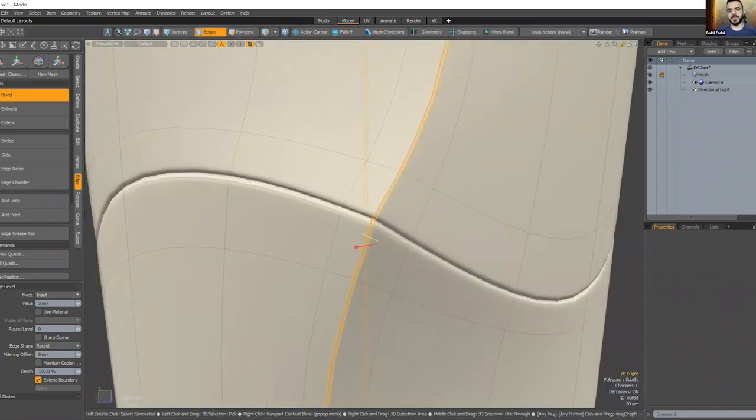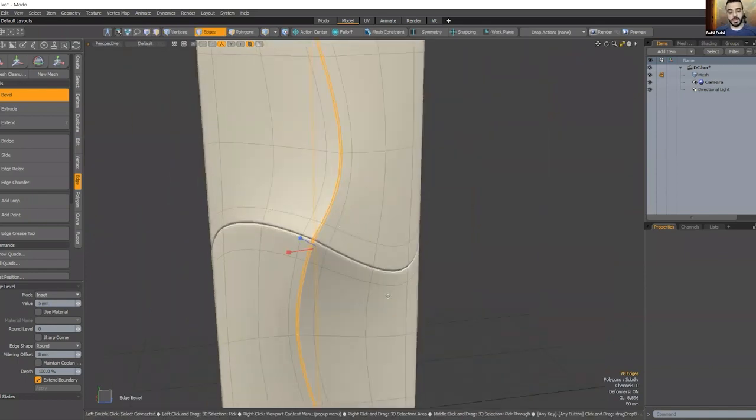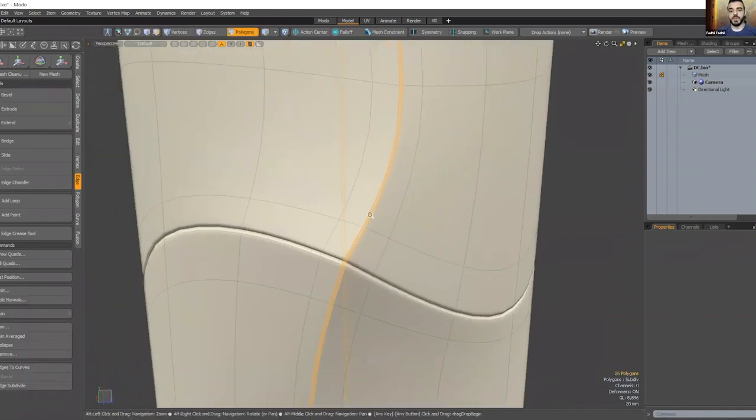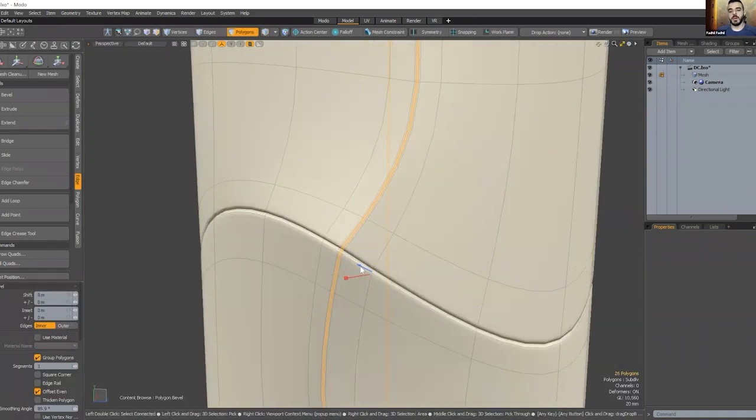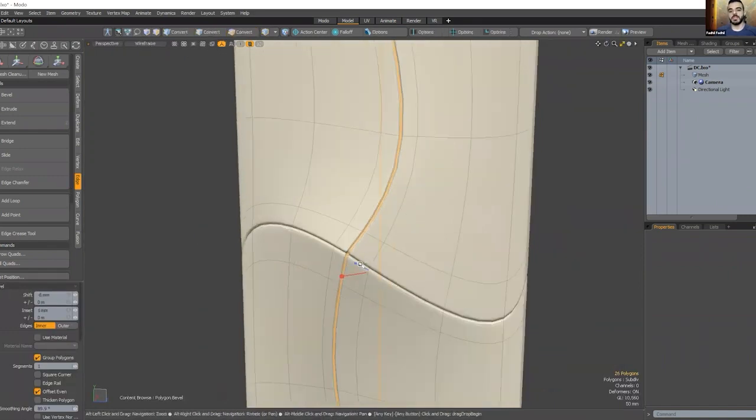And I'm just going to adjust it a little bit. I think we did 5 mil before that, so I'm just going to go ahead and do 5 mil. And then I'm going to hit B. I'm going to go ahead and, as I was saying, Alt-3 is to select the polygons that are in between. And then you hit bevel, and that's the opportunity for us to add another seam in between. And that, for me, is the joint system.